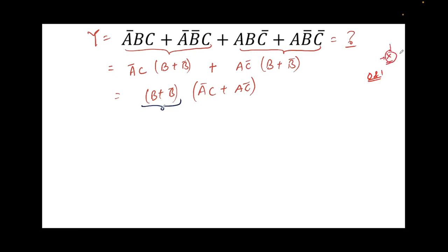When we do Karnaugh maps, K maps as we call them, then we encounter this entity, this unknown quantity, which can be anything, 0 or 1. Usually if nothing is said in your question, you just assume that it's either 0 or 1. It cannot be both. So you are correct. We'll see why B plus B bar will come out to be 1. But it's not always true. Remember that. In most of the questions, it will be true. So again, if nothing is said in the question, we'll assume that B plus B bar is 1.